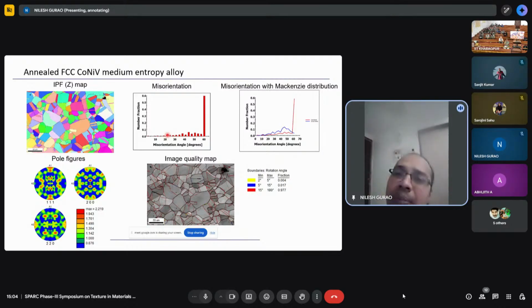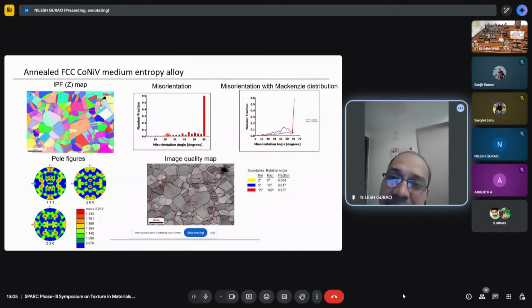I gave you just a simple thought problem. And that's why I'm saying, let us revise the basics, right? So simply, if you were to do horizontal or vertical grain size intercept on this microstructure, what is the grain size you are going to get? a by 2, right? Yes or no? And even if you get this measurement, the way I do averaging, I could do number averaging and area averaging, right? So does everyone agree with me? Everyone is getting an answer a by 2, both number average and area average? Yes, sir. We got it.